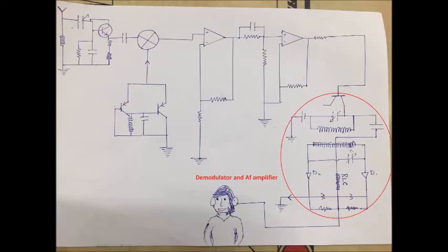Okay, so this particular demodulator is the Foster-Seeley demodulator. You can see it takes the input across the capacitor, and also it has a reactance in the center of the circuit which is very high, so as to provide the minimal amount of variation in accordance with the input. Also, there is a variable capacitor to provide the natural frequency for the given voltage which is coming from the input. So the basic aim of the demodulator is to keep the amplitude proportional to the change in frequency. And why is this done? This is primarily done in order to separate the information that was modulated on the carrier from the carrier wave itself. After all, we want to get only the things that we wish to get. So in lieu of that, the demodulator functions accordingly.